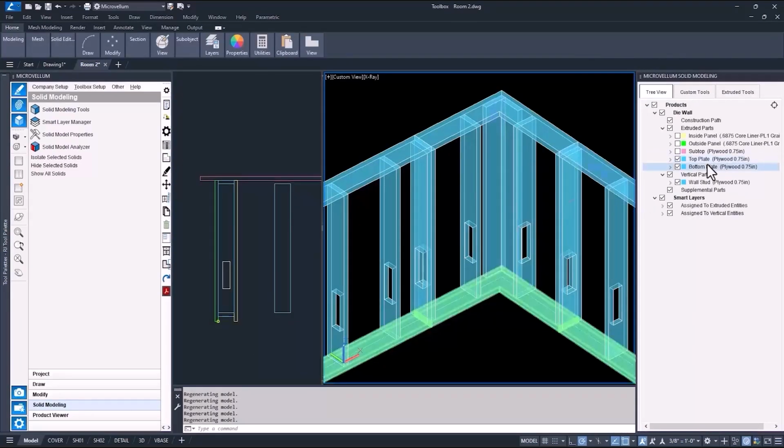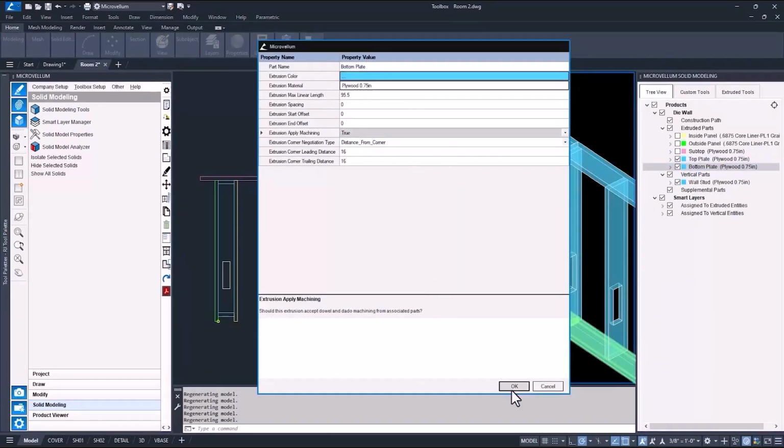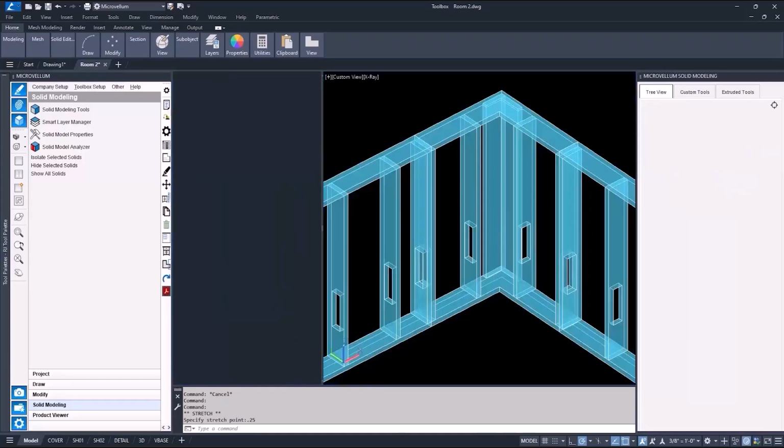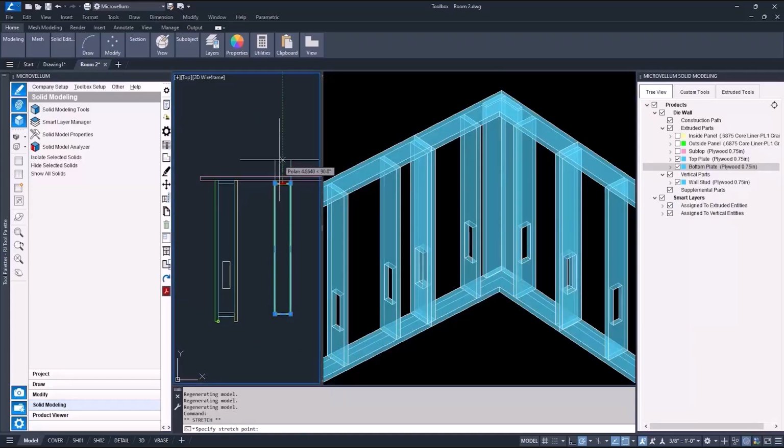Then finally, the last thing to do, after updating the settings, is to adjust the size of the part. And then, of course, if there's an alternate profile, make sure to adjust that too. Now, the dado depth is going to be determined by how much you add to the part. I'm going to add 1/4 inch to the top and bottom.